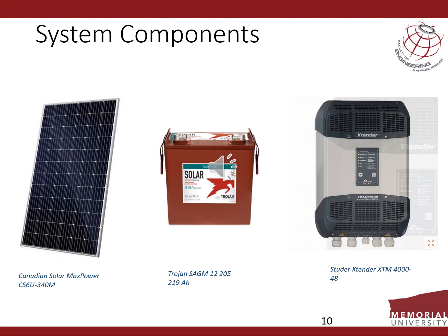Our batteries are 12 volts, so four batteries will be connected in series to make one string, and the whole system will be optimized by HOMER Pro software, so that we can find out how many panels, how many batteries, and how much inverter capacity is required. So these are the three main components of our system.